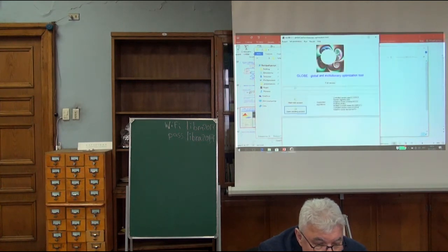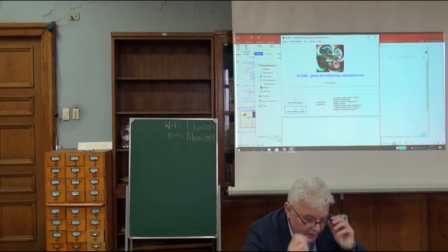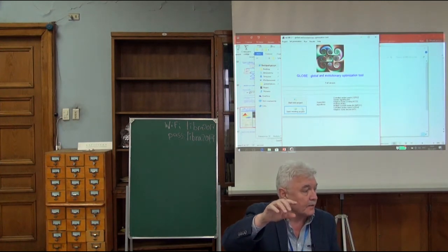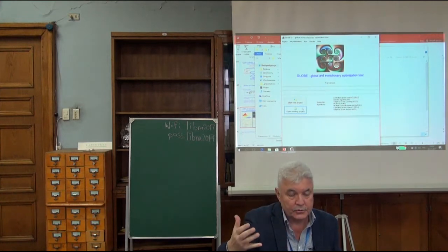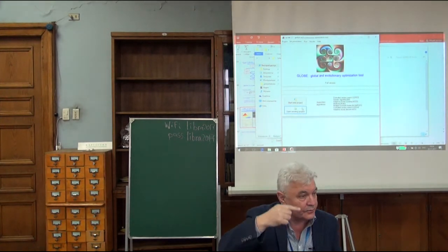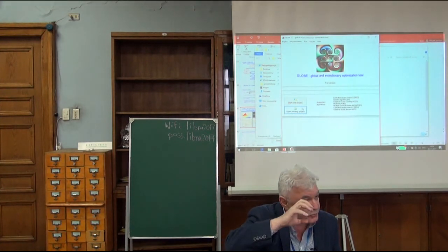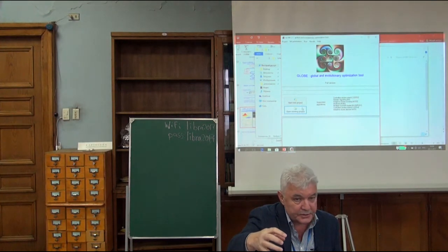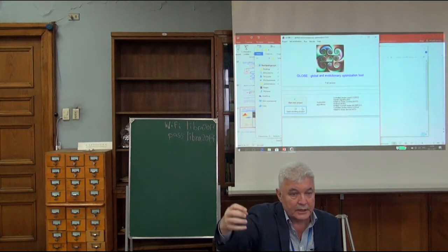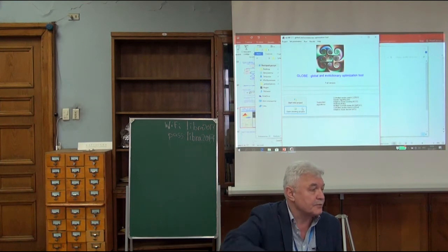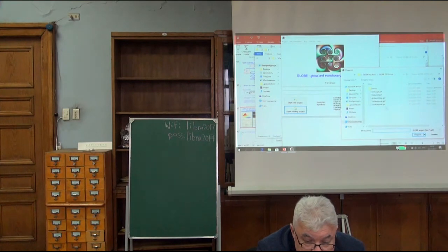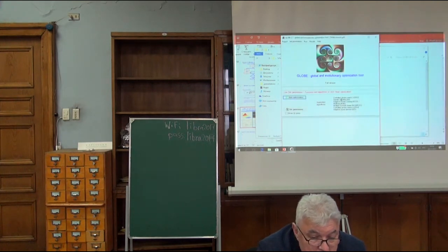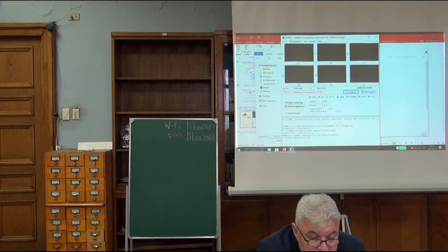So what this tool is doing is this: I have an implementation of this tank model, and there are 8 parameters to calibrate, 8 which we don't know, and we run this model hundreds of times in a loop, every time generating a new vector of parameters, 8 numbers, running the model and calculating the error. And we use the adaptive cluster covering algorithm that I explained, or we can use a genetic algorithm or anything else. Okay, so now I will start the optimization, and here you have buttons which we could run in steps.